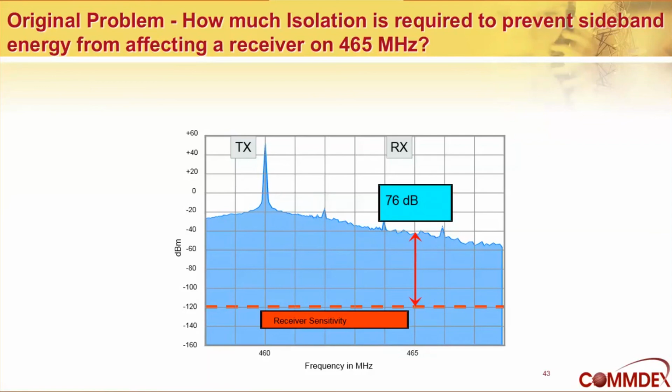That's what we want to get. Anything above that, we're going to hear the noise, and we don't want to hear the noise. Nikki says she got it now. She understands, so you can move on. And Nikki's question: the minus 120, Nikki, that's a typical receiver noise floor. You get into the noise temperature. She asked a question, so I'm just trying to help move along. It's the noise temperature of the system. So if you look at minus 120, that's kind of a good basement. I think we're good, Bruce. Thank you. Okay, thanks.